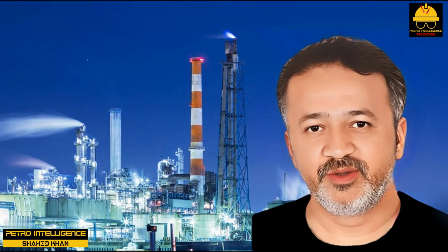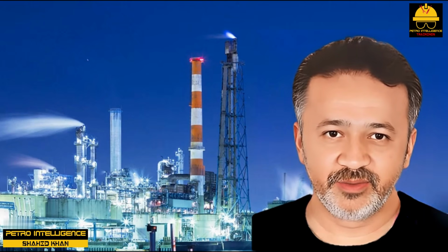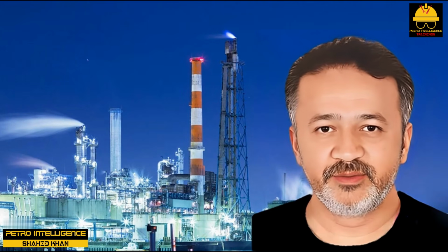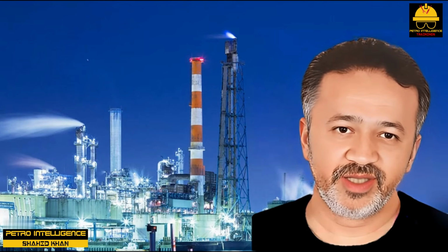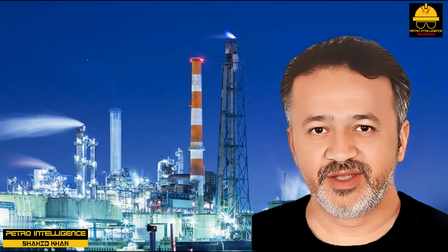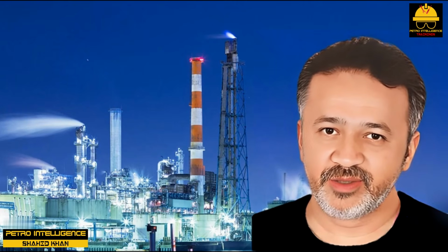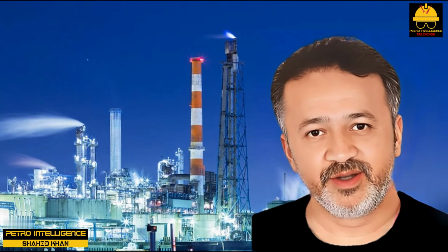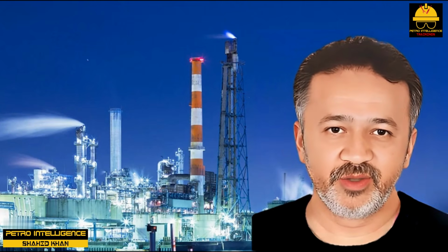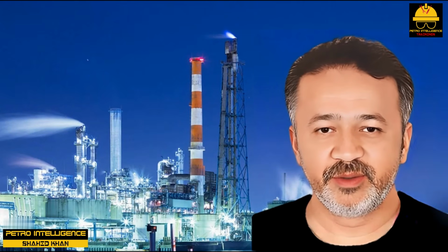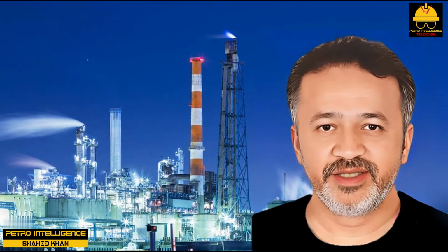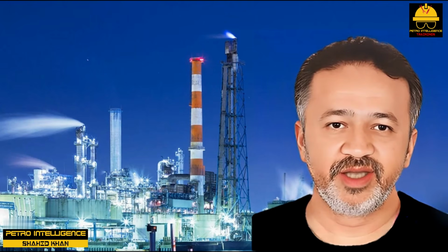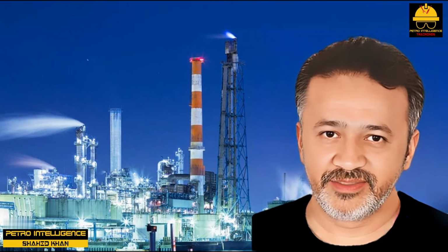Oxygen can be drawn into the refrigerant loop due to minor air leaks in the suction piping. To avoid this potential hazard, one should always maintain a positive pressure at the suction of any refrigeration compressor. To overcome this limitation, he increased the propane content of his circulating isobutane refrigerant from 5 to 10%. This required several hours. As the suction pressure rose due to the more volatile refrigerant, the operators increased the refrigerant compressor speed, and hence the refrigerant circulation rate. Eventually, using this and other tricks, he increased unit capacity to 25,000 BSD.